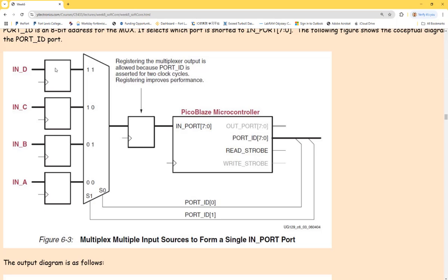Okay, so whenever you use a port ID like an address, so I want to pick up, for example, port 10, and port 10 will be the ADC's output, and eventually the ADC's output, that one byte, will be sent to the CPU through the port.